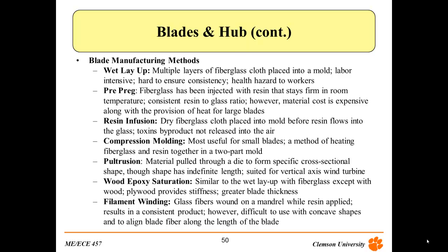Resin infusion. Dry fiberglass cloth placed into mold before resin flows into the glass. Toxic byproducts are not released into the air. Compression molding. Most useful for small blades. A method of heating fiberglass and resin together in a two-part mold.